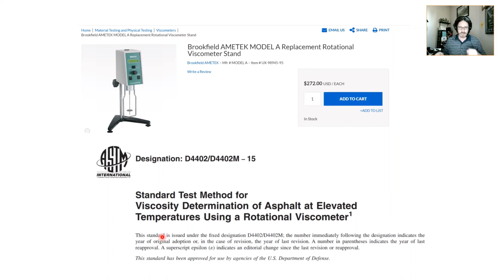This looks more like a rheometer. Viscometers and rheometers kind of do the same things. Some people like rheometers, but a lot of times rheometers give you similar information to a DMA, so I still like the DMA. Anyway, this is a viscometer. It's like an egg beater kind of thing, and you measure the resistance to the shaft turning the little beater unit. That's how you figure out your viscometry, and there's an ASTM standard for that.